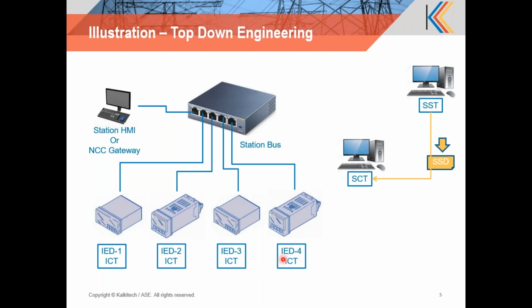Okay, so he solicits ICD files from the ICTs, the IED configuration tools of the selected or participating IED models. Nowadays, in the times of multifunction devices and highly configurable devices, this stage typically involves some amount of pre-configuration of these IEDs, which could involve changes in its data model or changes in its services to fit the envisaged role. The SCT user has a picture of what IED fits what role in the specification, or what IED can be made to fit what role in the specification by making small changes at the local level.